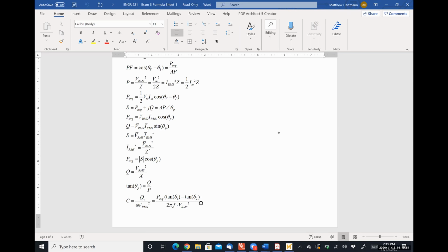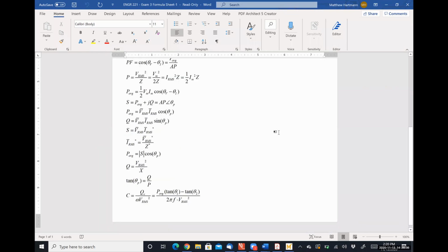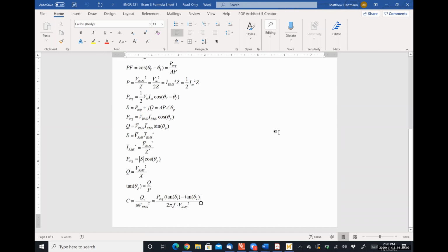So Q_C is always going to be a negative quantity. Dr. Cronk just left it off of here for whatever reason. Does it say anywhere on there what C is? Doesn't look like it, not my problem. I'm going to allow you to use this stupid equation sheet, but I do not agree with you getting to use it. So is the real part always going to get removed? Yeah, it's always going to get rid of the real part, and that's the whole point of power factor correction.